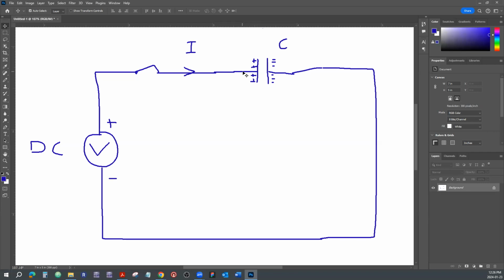But if you have, at the beginning, the maximum inrush of the current, well, because it's going to act as a short, then the voltage across it is going to be zero. It's just like a straight wire. If you put a voltmeter across a straight wire, the resistance of that wire is pretty much zero, so you're going to have the voltage equal to 0 volts.